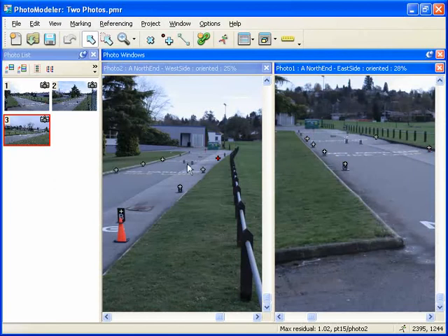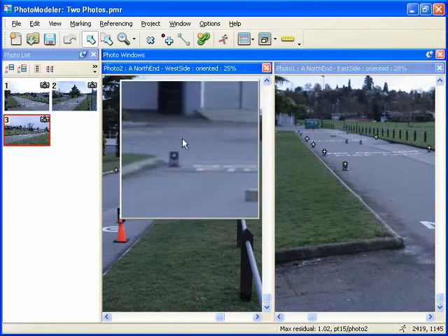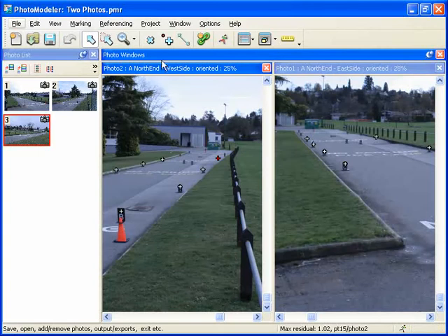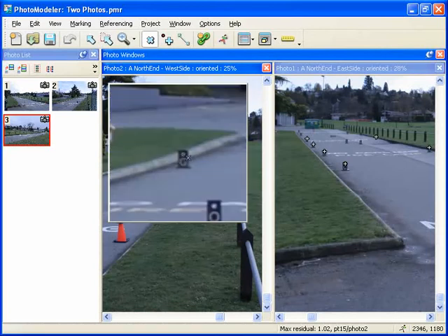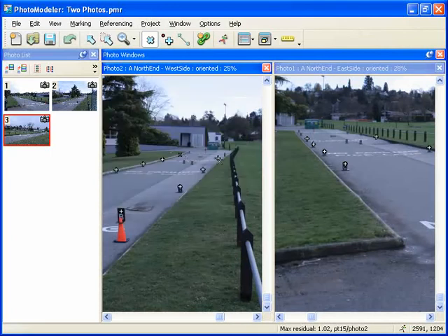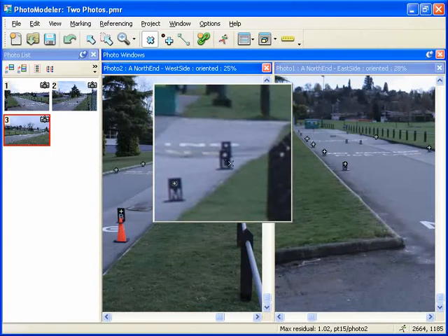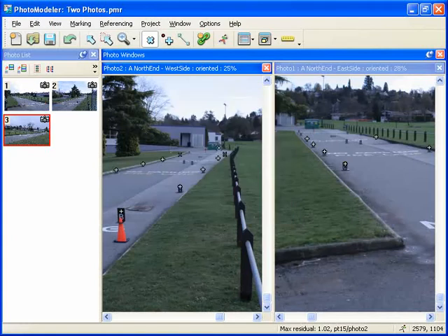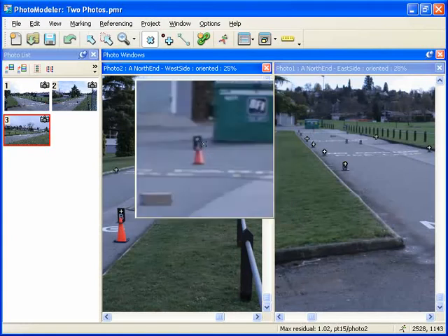The targets here are too small to identify using Subpixel mode, so we will manually identify the centers of the targets using Mark Points mode. Hold down Alt. Carefully mark the center of target G, and the same for target L. The target behind it, the furthest point away, target J, and target H.